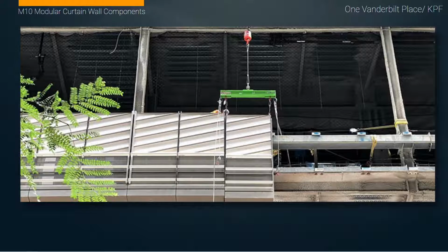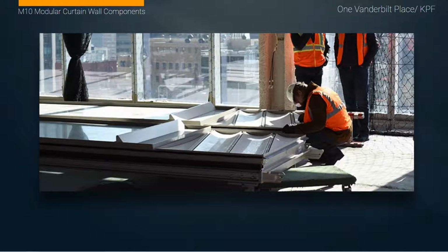This is a starting unit, so actually what happens is that you get an idea of the relationship of the terracotta panel to the floor system. So these panels are actually starter courses. So you have some kind of a transition down to the podium and then the start going up of the unitized assembly. And here's a shot of the module being staged for installation. This could be someone checking the clip systems or preparing this panel for being craned or lifted into position. You can see now the terracotta panels at the base. Up here we have the glazing system.